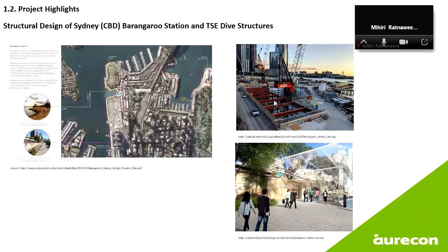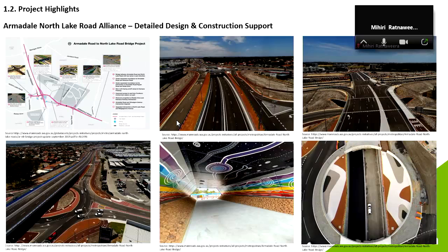Typically you get surcharge load or reaction from the train station above the underground structure, and you just have to design the underground structure to support the reaction. But in this project, the design of the underground structure is a package of its own, because you have all the soil pressure on the side as well as the hydrostatic pressure, because the water table is so high, and the design groundwater table during a flood event is even higher. Making sure this bathtub doesn't get floated and flushed away was quite a challenge. We basically have to consider all the dead load with safety factor, and also rock anchors into the foundations underneath.